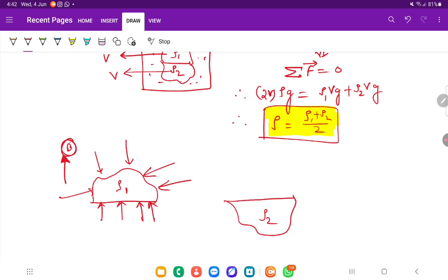And that is what buoyancy force is. This is the origin of buoyancy force. It is just the hydrostatic force, and as different heights will have different pressure values, whenever you go down the depth, the pressure value will increase and automatically the force will also increase. So there will be a net upward force that will create the buoyancy.